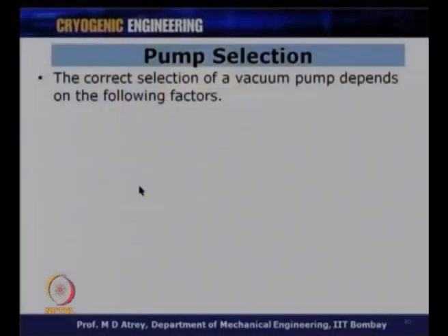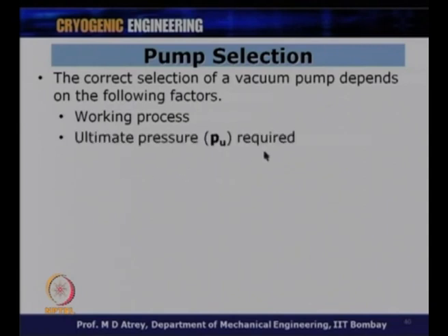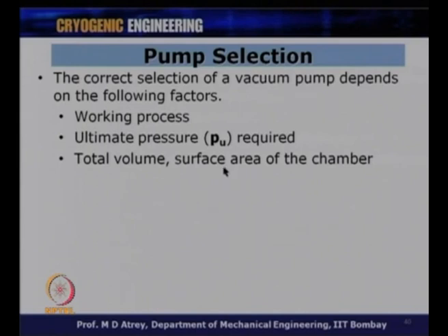The pump selection is governed by various criteria. What is the working process? What kind of pump do we want to use? Do I want a rotary pump or a diffusion pump? As I said, if we have a clean vacuum requirement, I should go for a cryopump and things like that. So, working processes, ultimate pressures required, total volume, surface area of the chamber to be evacuated, outgassing rate